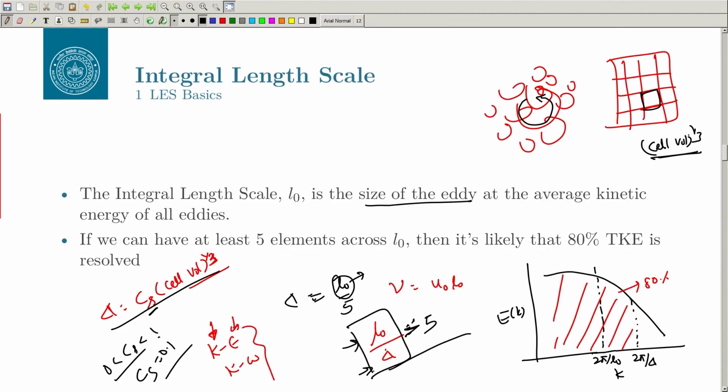Okay, you can make a contour and see what are the regions where you need to resolve. There will be some regions where this value is less than 5 and that you need to resolve, and once you do that, then that mesh will likely be basically good for your LES simulation, and then you can make it probably 3 dimensional and do the LES simulation.